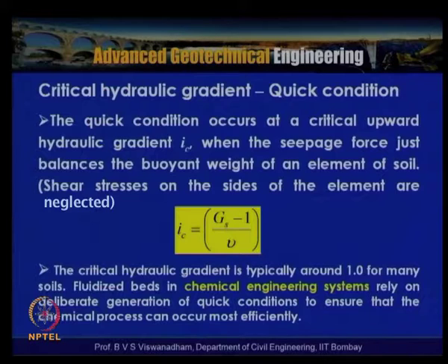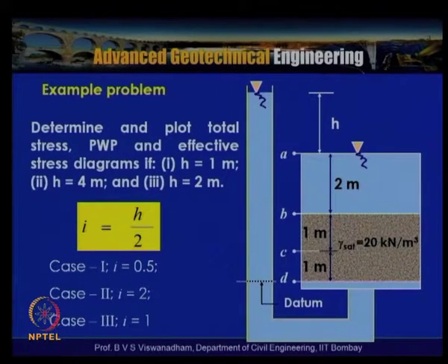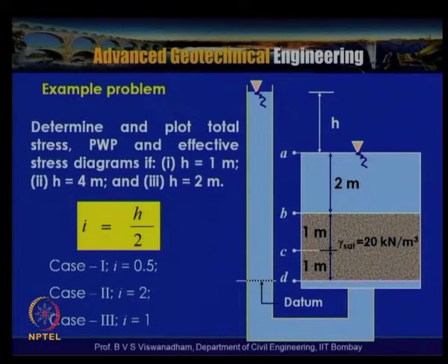In considering these deliberations, what we have neglected is the shear stresses on the sides of the element. So let us consider another example problem. The problem is described like this. We need to determine and plot the total stress, pore water pressure and effective stress diagrams for case 1, H equal to 1 meter, case 2, H equal to 4 meters, and H equal to 2 meters.